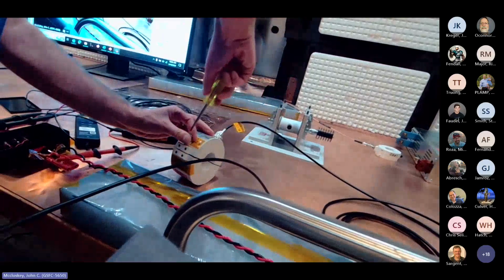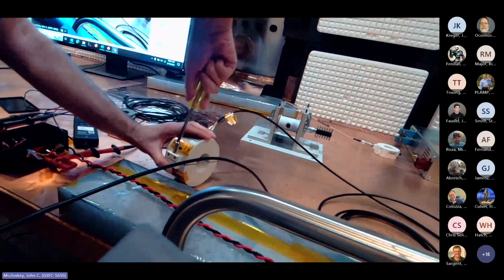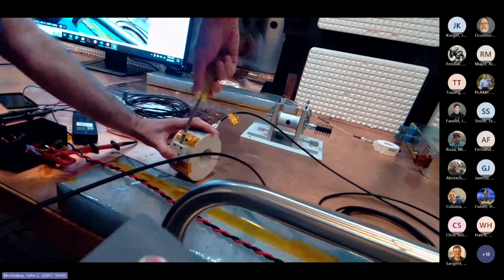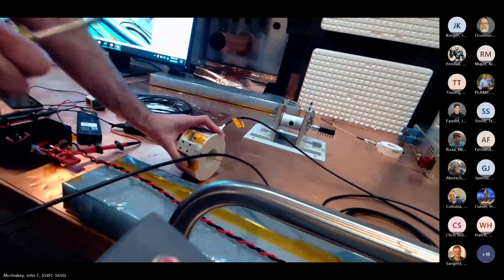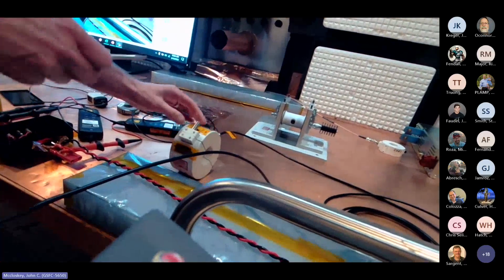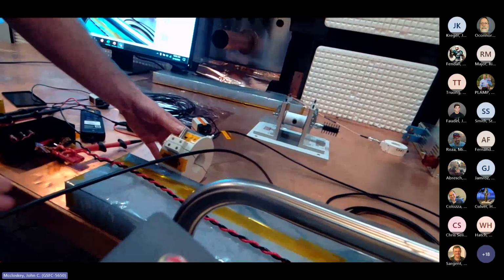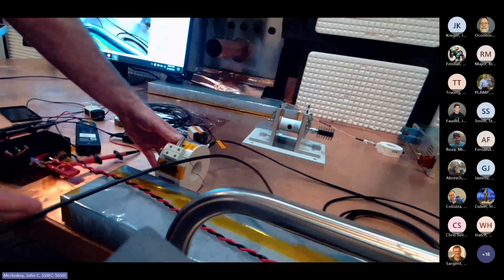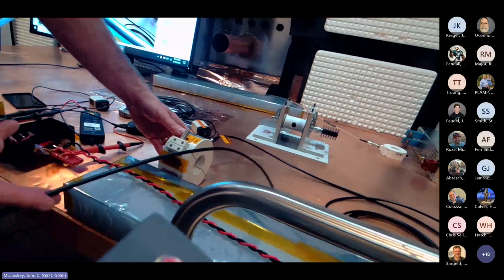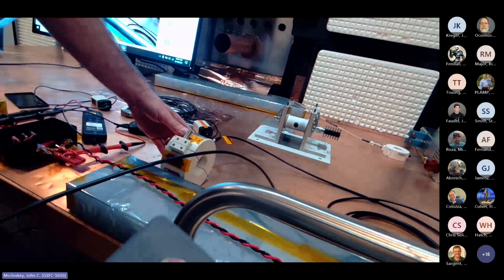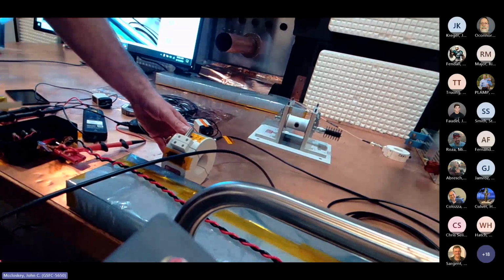Now, after you've done your calibration, you generally want to keep everything in your drive circuit exactly as it was. So same cable, because even though up to 200 megahertz you shouldn't have a whole lot of loss, cable loss tends to be a lot more prominent getting up to a gigahertz.